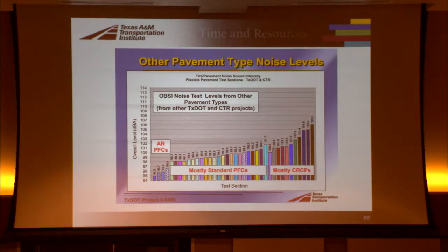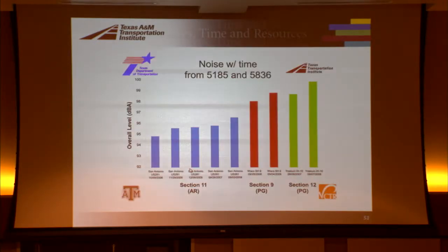In terms of noise level, the asphalt rubber PFCs, you can see here, have been considerably lower noise than some of the standard PFCs. And compared to CRCs, there are actually some low noise CRCs I'll discuss in a little bit, but you can see here that asphalt rubber actually showed considerably low noise. And here are some tests from a couple of TTI projects, where the asphalt rubber did pretty well in keeping its noise properties over time, and it's